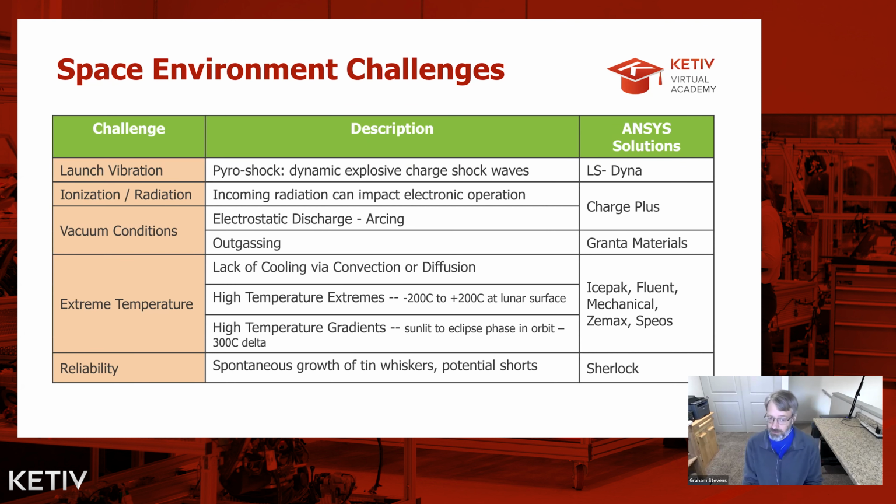And also under vacuum, you have outgassing that might happen. And so we may want to examine our materials for outgassing. Then we have temperature extremes in outer space. A big issue is how do I cool my electronics? How do I cool my assemblies?